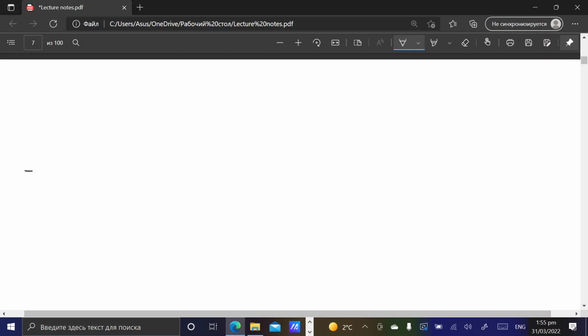So we have the Fermi energy for the metal. For metal we don't show the valence and conduction bands because they overlap with each other, so the only thing that matters is the Fermi energy. Here, let's draw the vacuum level. So this will be the work function for the metal. Let's call it W_M.